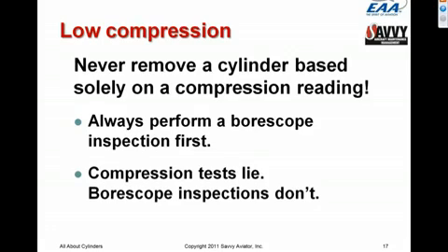At any rate, because the compression test has so many artifacts and there's so much noise on the data, we never ever want to remove a cylinder from an engine solely based on a poor compression rating. What we want to do is always stick a borescope in the cylinder and look around and find out what's really going on in there. Because compression tests lie, but borescope inspections don't. The borescope is the gold standard for cylinder condition nowadays. And we still do compression readings because the regs require that we do them, but what we see under the borescope is much more important than the compression readings we get.